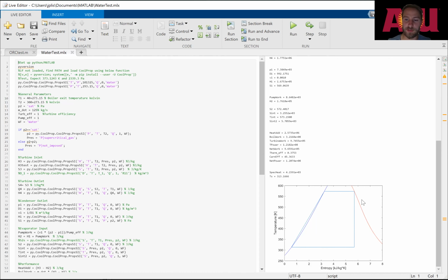And if we were to see this like for the ammonia and propane curves, we knew right here that we could use a wet fluid pump. And once again, that's just good if we were to move on to prototyping or to move on to testing different working fluids. Knowing whether we needed a dry or wet fluid pump could help us out in the future quite a bit, either to save money, to plan for which working fluids to use, and what is practical use in a residential environment. So that is just a quick overview of the function we developed.